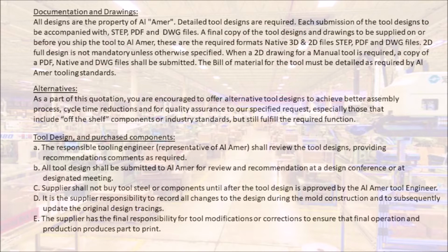Tool design, and purchased components. A. The responsible tooling engineer, representative of Amer, shall review the tool designs, providing recommendations, comments as required. B. All tool design shall be submitted to Amer for review and recommendation at a design conference or at designated meeting. C. Supplier shall not buy tool steel or components until after the tool design is approved by the Amer tool engineer.